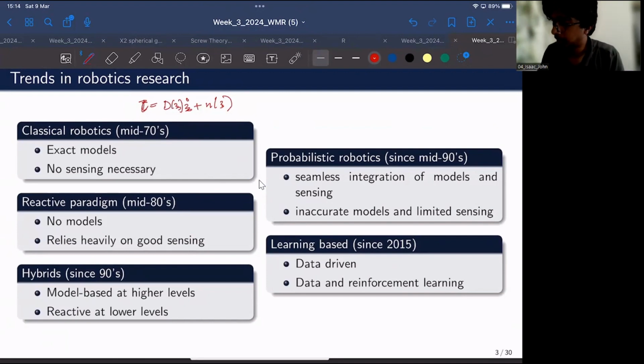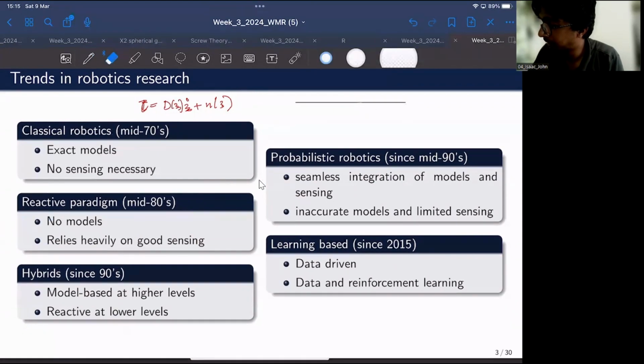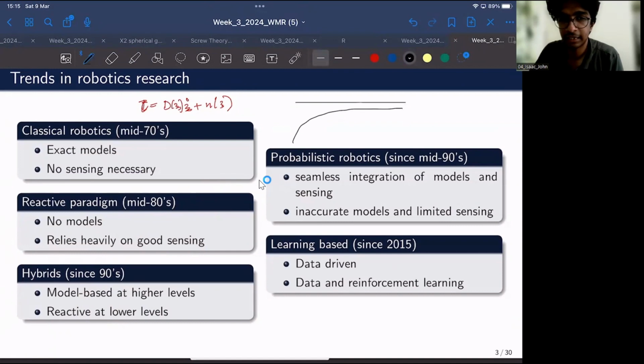For example, if your robot is having some sort of a steady state error, maybe the line I have drawn here at the top is the desired path or a desired parameter and your actual is only reaching a slightly different value, there is a slight deviation between the actual and the desired at steady state. You can compensate for this steady state error using the integral term, because this integral term would accumulate all the errors and eventually make this error disappear as time goes to infinity.